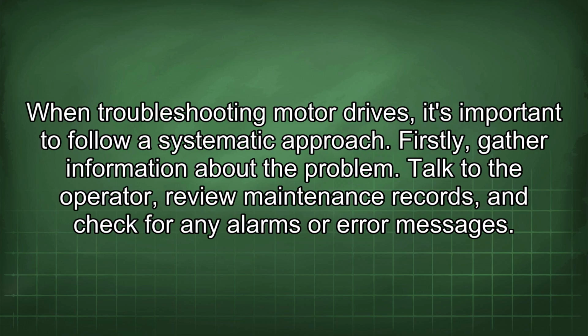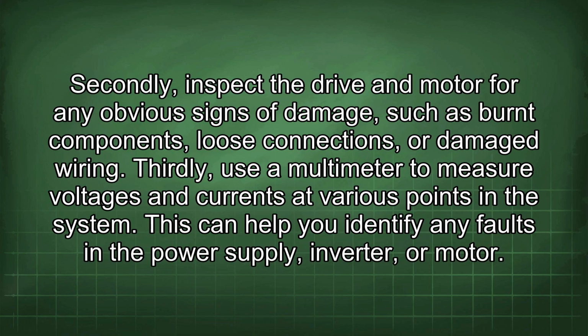When troubleshooting motor drives, it's important to follow a systematic approach. Firstly, gather information about the problem. Talk to the operator. Review maintenance records and check for any alarms or error messages. Secondly, inspect the drive and motor for any obvious signs of damage, such as burnt components, loose connections, or damaged wiring. Thirdly, use a multimeter to measure voltages and currents at various points in the system.